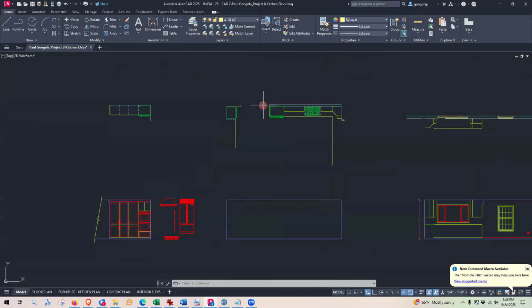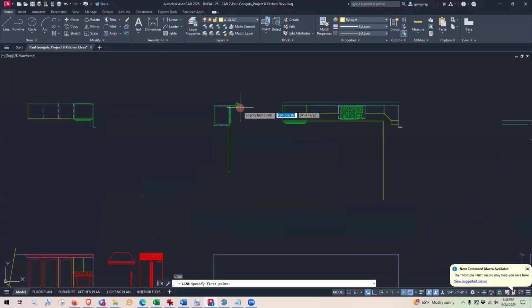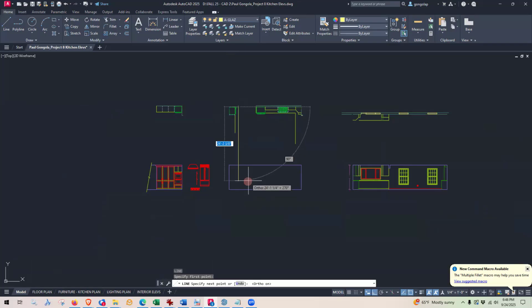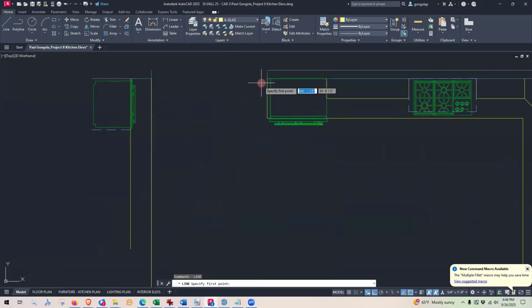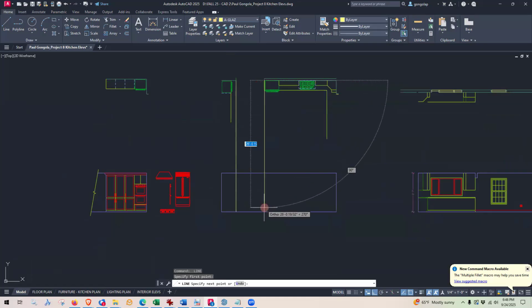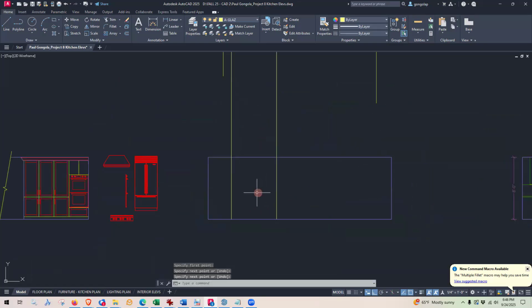All right, so I have this little opening here, and I'm going to come down and mark the sides. These are the sides of the opening. And then how high do I want my opening? Probably 7 feet. The height of our space is 8 feet. So I'm just going to draw a little line 7 feet across. And then I will fill it or trim.